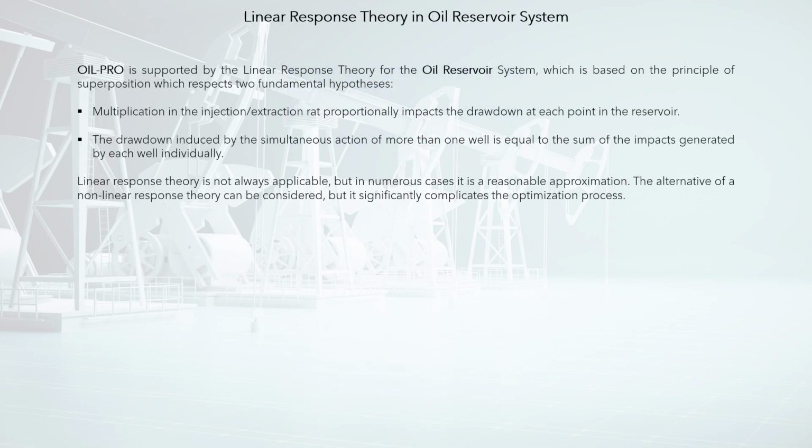The models supported by the linear response theory for the oil reservoir system are based on the principle of superposition, which respects two fundamental hypotheses. Multiplication in the injection, or extraction rate, proportionally impacts the drawdown at each point in the reservoir, and the result, drawdown, induced by the simultaneous action of more than one well, is equal to the sum of the impacts generated by each well individually. Linear response theory is not always applicable, but in numerous cases it is a reasonable approximation. The alternative of a nonlinear response theory can be considered, but it significantly complicates the optimization process.